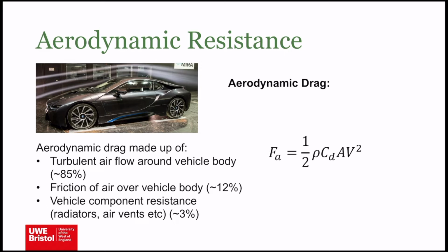And then, notice we've got a V in there, how fast you're going, and it's squared. Okay, so you double your speed, your drag's going to go up by 4. Okay, so like I said, vehicle speed is very, very important when it comes to increasing the aerodynamic drag, which is why going from 70 to 80 on a motorway,